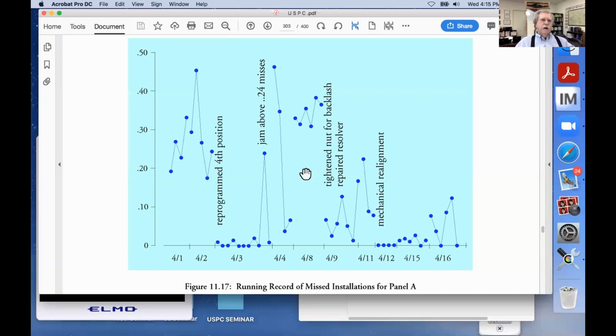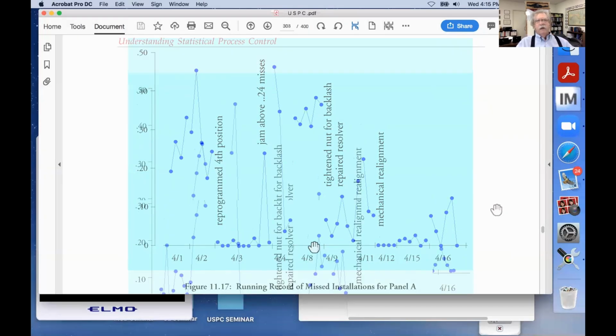Now, these robots are in a trim plant. They're cutting velvet with saws not 50 feet away from these robots. A trim plant is almost like a textile mill. The air is white with lint. Lint is not a friend to robots. They figured out drop nuts was one of the causes they were dealing with. They started cleaning out the vacuum filter every day, and drop nuts went away.